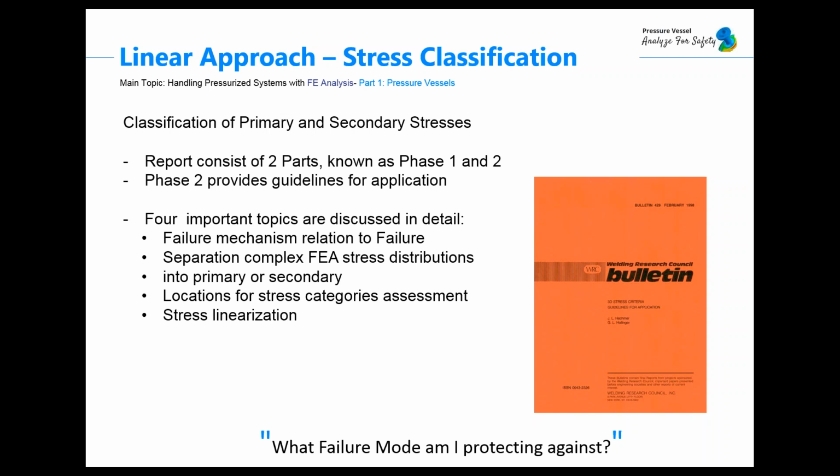And there have been a number of discussions of this topic. You can find a lot of information on the forums. But the object of the whole exercise, I mean the object of the stress linearization, is not to find a linear profile of the stress, but actually to sort the statistically determinate stress components from the indeterminate components and peak stresses.